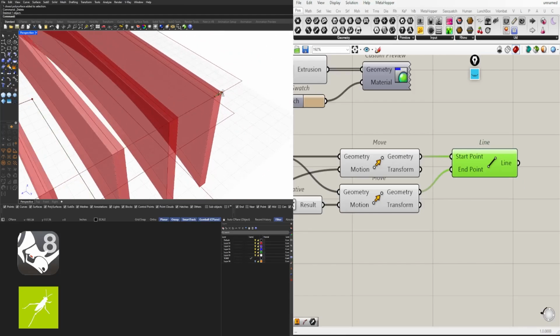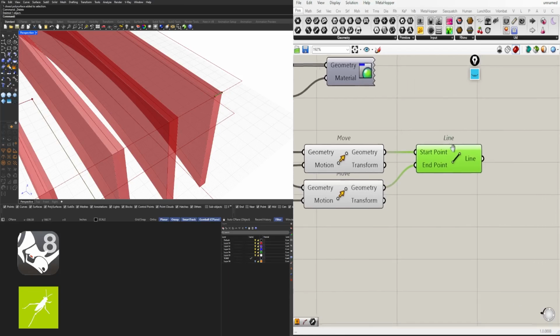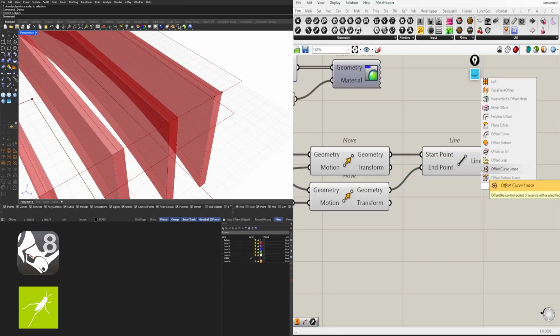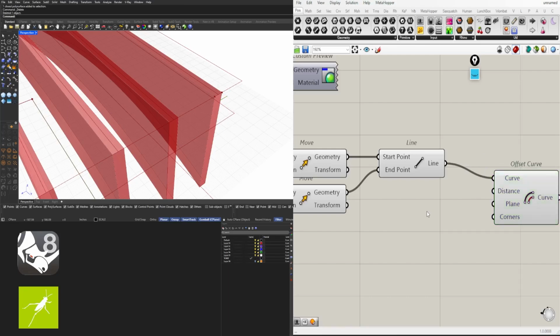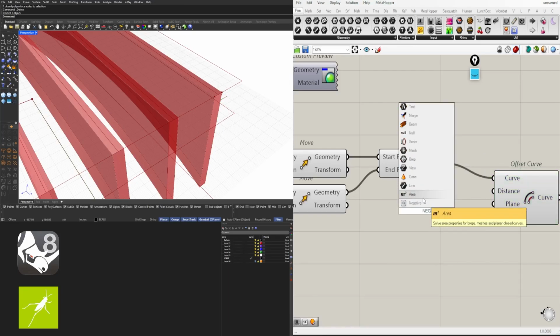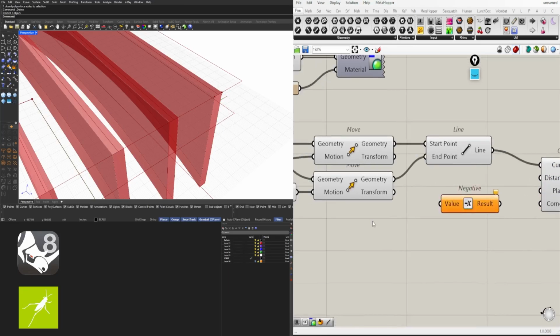Now to create that bracket, we need to offset it to this side, to the inside. So offset. And when you offset something, it's going to go perpendicular, so we don't have to give it a specific change of vector or anything. With the line segment, now we know it's going to go positive or negative. Here, it's going +1. So we'll actually go to a negative and then use a number to create the size of the bracket. So this is up to how you want to manufacture this. We'll go 2.5.